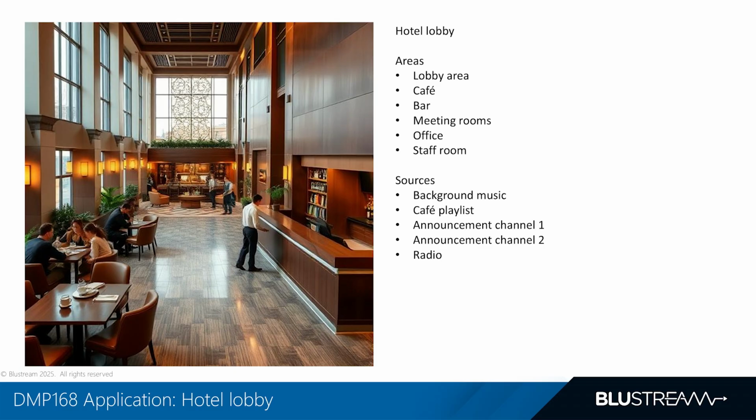Now, here's the challenge. We need background music in the public areas. Two microphones have to be integrated, one for general hotel announcements and one for the restaurant. The staff wants radio in the office and lunchroom, but they also need to hear announcements so they don't miss important messages. We also need hotel-wide announcements that have to play in both the restaurant and the bar. With the DMP168, this setup is simple.